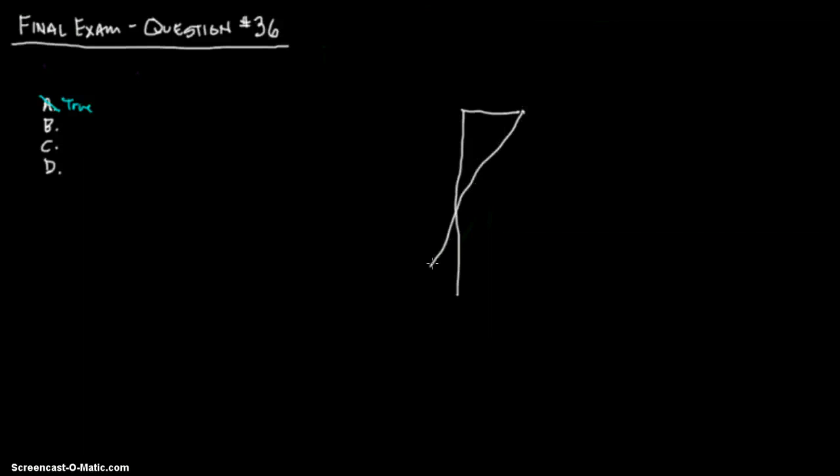So let's say that this, and this is obviously not to scale. We're going to assume this is, taking a look at the cross section, this is a stress diagram. And in concrete design, you're going to have a tension side, which tension is going to equal the area of your steel times your yield stress of that steel, which is usually 60 KSI. Area of steel, you get your number of bars times the bar area.